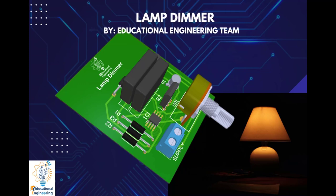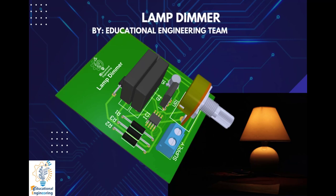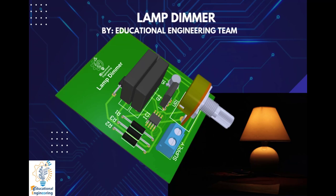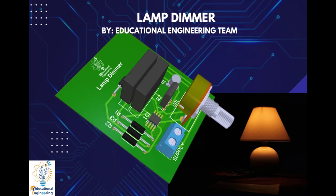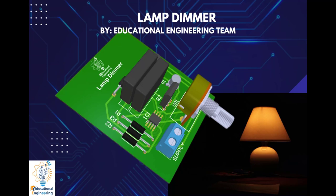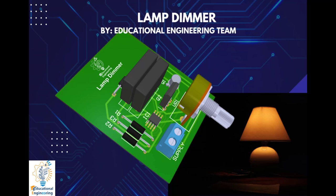In this circuit, the IC555 is wired as an astable multivibrator and it gives continuous square waves as output. The resistor and capacitors are the timing components. The duty cycle of the wave makes the lamp dim or glow brighter. The higher the duty cycle, the brighter the lamp glows, and a low duty cycle will make the lamp glow dimmer. So now, let's start designing it using Altium Designer.